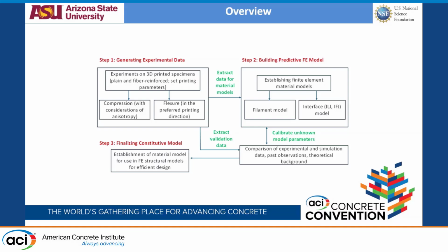And then we'll talk about how a predictive FE model could be built based on all these parameters, based on two of the cards I'll be using, one being the MAT 213 that I talked to you about, and another being a MAT 186, a cohesive zone element model for the interfaces. Then in between I'll talk about how the calibration process was done, how we are ending up with the results we are ending up with, and how this will be a constitutive model for predicting the failures and predicting strengths based on different mechanical tests.